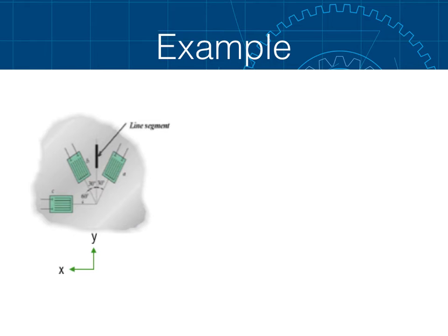From this original picture, we can see that strain gauge A is situated 120 degrees from the defined x-axis, which is pointing to the left. The strain gauge B is situated 60 degrees from the x-axis, and the strain gauge C is situated 0 degrees from the x-axis and is parallel to the x-axis.